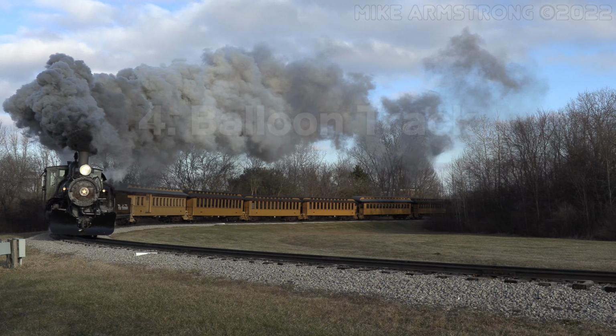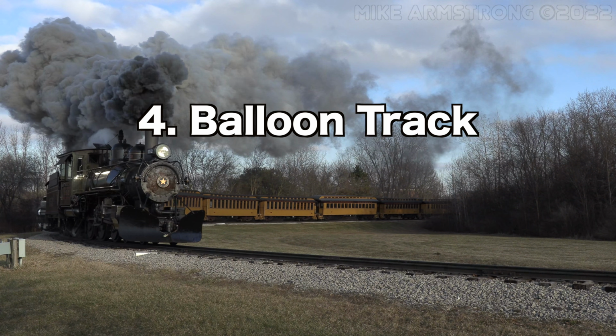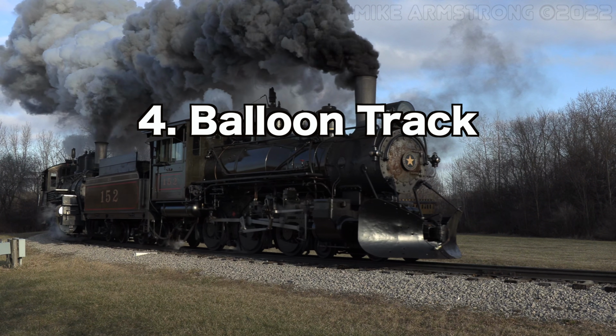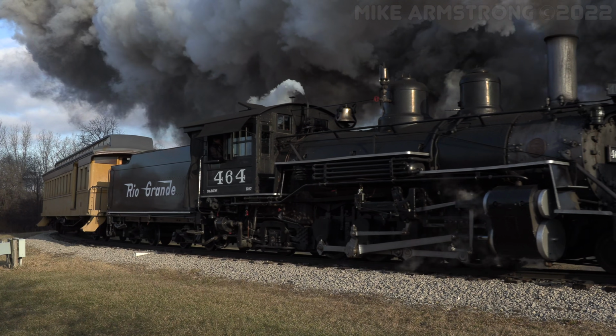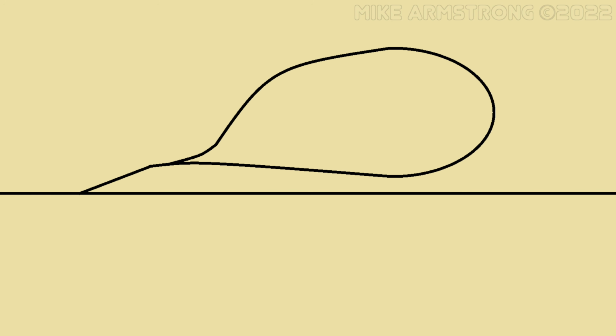The balloon track is the fourth option on our list for turning a train around. A balloon track is a large circle of track that is pinched off and connected at one end with a switch. Like the Y, a balloon track can be used to turn either an entire train around or just a set of locomotives. In this situation, a train proceeds into the balloon track and past the switch at the beginning of the loop. Once the end of the train has cleared the switch, it can be thrown so the train can then exit the balloon track, turned completely around and moving in the opposite direction from its point of entry.